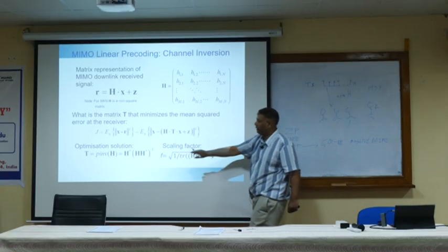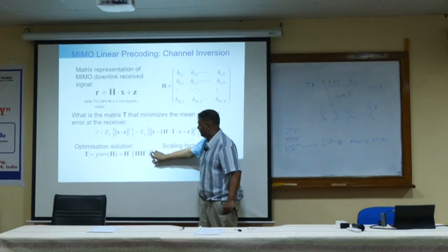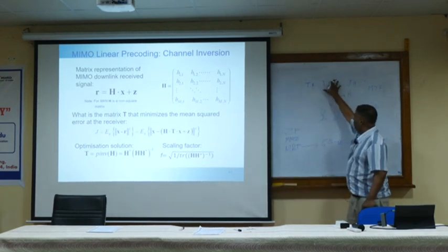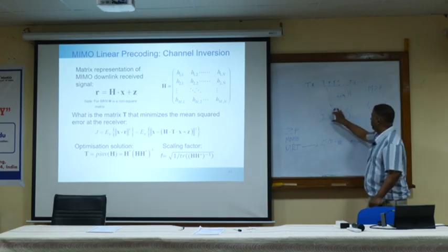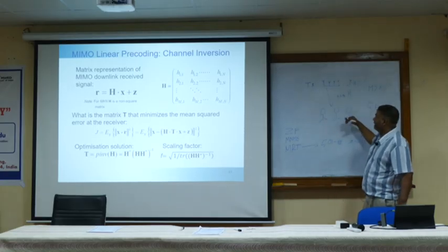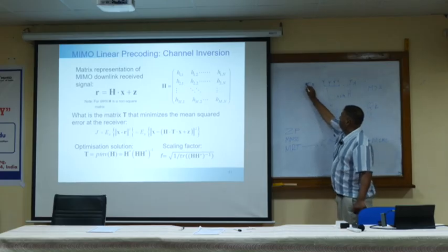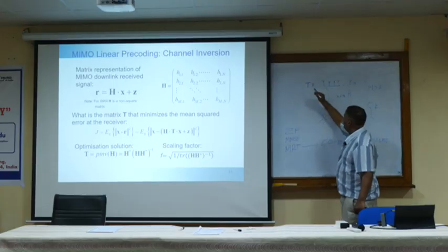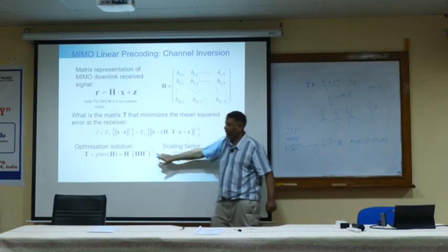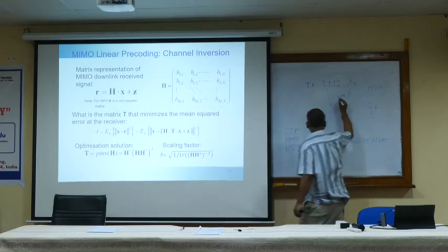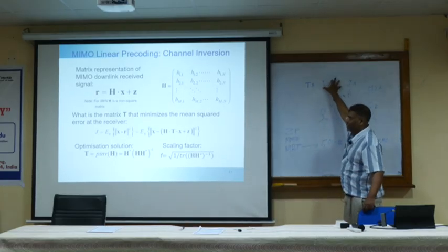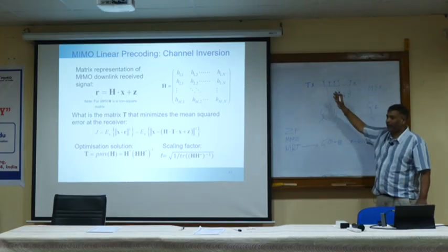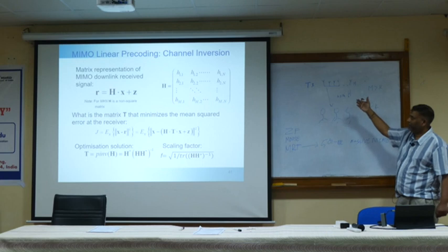It's given here for the zero forcing case. This is the precoder. So the base station wanted to send all information X, which contains all the user information. Before sending that information, it multiplies it by a matrix called the precoder. You can see the precoder needs channel knowledge. This channel knowledge has to be known. That's why, in an FDD system, all the users estimate the channel and feed it back, and in a TDD system, channel reciprocity is there.